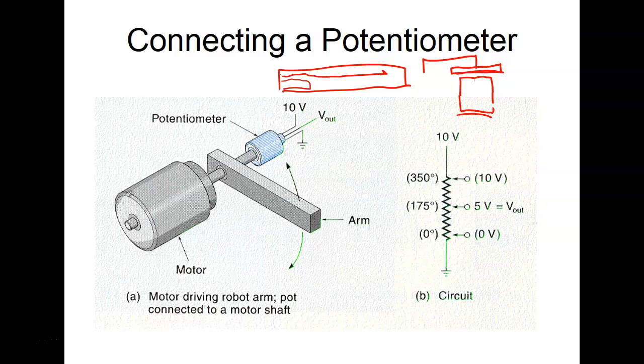That's a really good question. We've got two manufacturing lines over there, and both of them use a potentiometer to check position, but it's actually giving us height, right? One of them is truly a position. It moves across, we have magazines down at the bottom, and we can program it to stop. It knows when it's at a magazine when it gets a certain voltage.